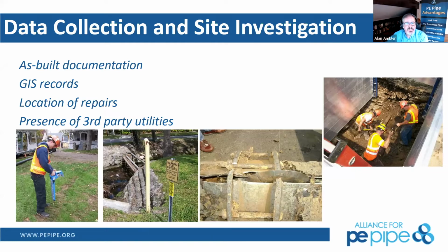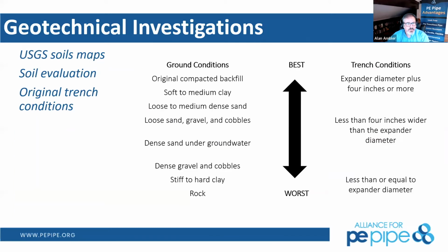And then we had another question about bursting 2-inch HDPE or PVC. One of the problems and challenges with smaller diameter pipe may very well be the same in fitting that cable through that pipeline itself. The lateral bursting rig that the Alliance for PE Pipe uses on the show floor has a smaller cable that is intended to be in pipe sizes 6 inches and smaller, and you may very well be able to insert that into high density polyethylene and then go from and cut through that at that juncture. So thank you very much, everybody, for the great questions as we go through, and we'll keep going.